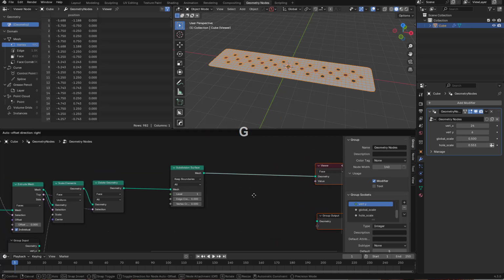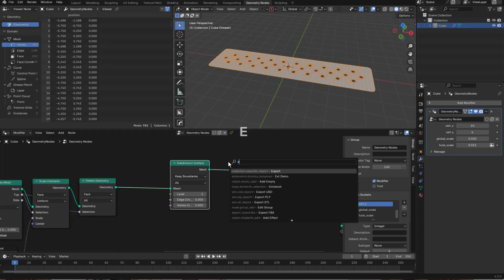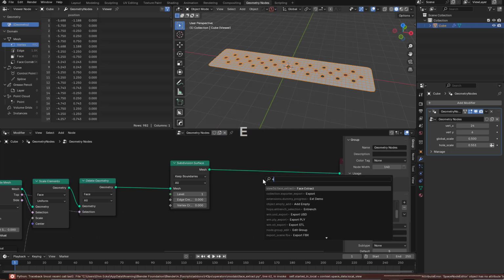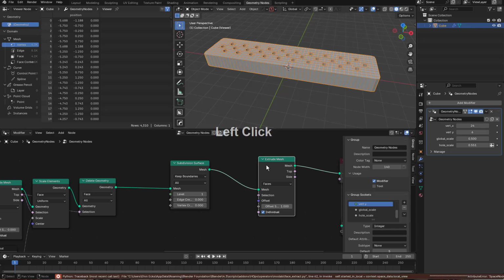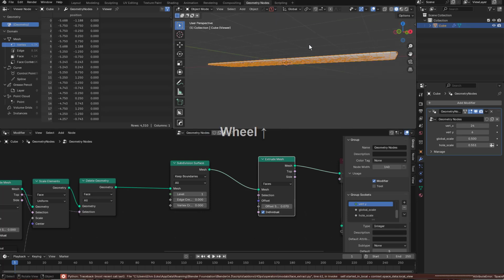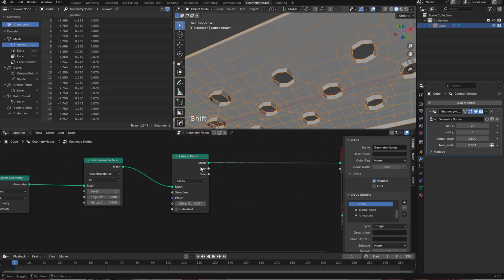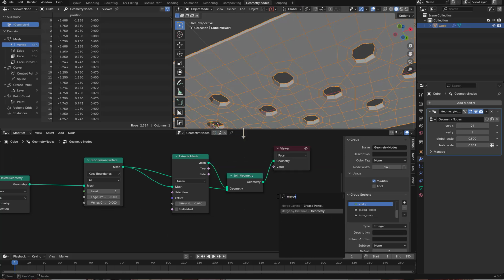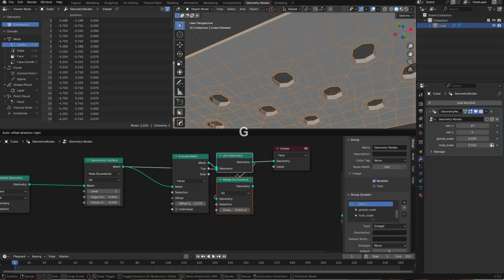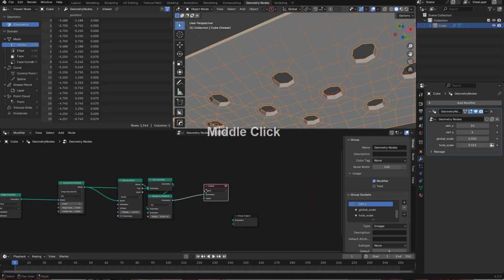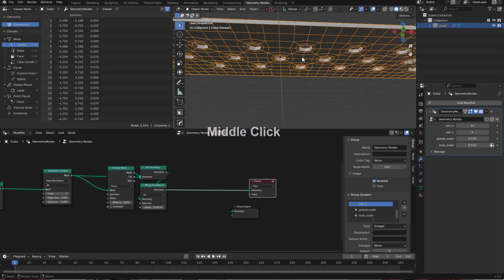What we'll do is go ahead and make it solid, and for me, making it solid is extrude. So we'll extrude the mesh. I accidentally tried to use a mesh operation in the node editor just now, causing an error. I have to make sure that doesn't happen. Let us join, and what we'll do is join the original mesh, and what we'll do is merge. And now that we have merged, this geometry is now solid, manifold, and thick, and we can just adjust our extrusion amount here.